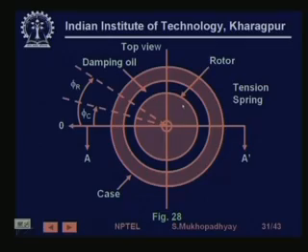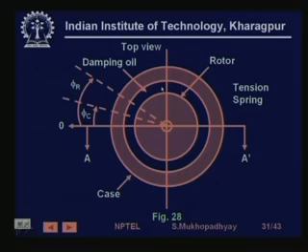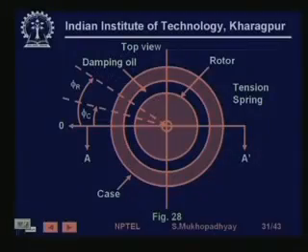Again we have this rotor which has some moment of inertia, which is the rotational equivalent of mass. We have damping oil which gives you friction, and similarly we have some torsional springs. So you again effectively have a mass spring damper system, but now in rotational terms. So you can have both.